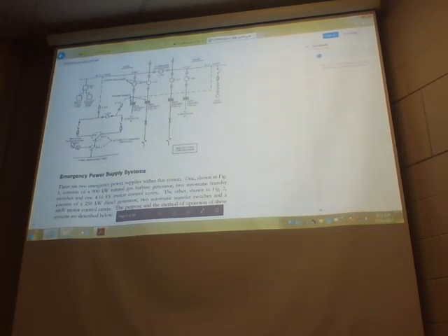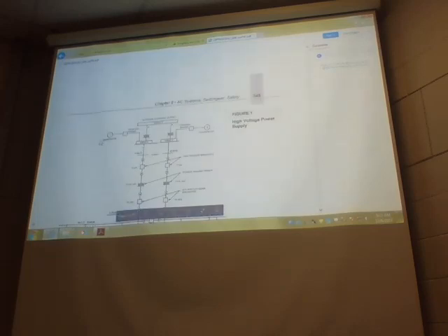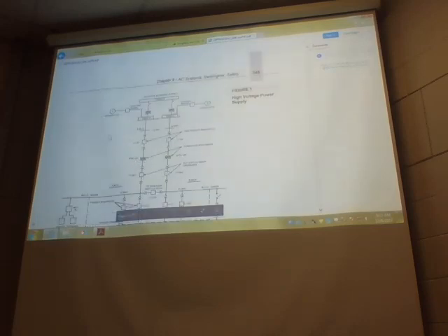So this natural gas generator is able to feed into the system here if power is lost back here and you don't have access to the other bus, like closing the switchgear. So you do have an emergency backup generator here, which means there are now 3 generators involved: the 2 main ones for power supply and the emergency backup.